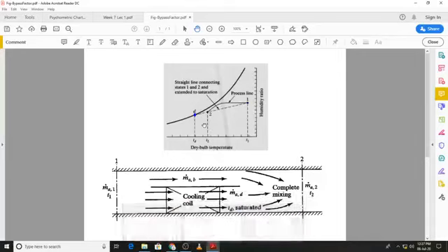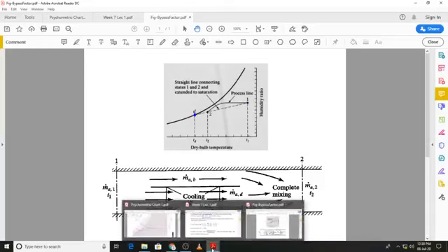So if we look at this figure over here, the difference between temperatures T2 and Td, that shows the effect of the bypassing of the cooling coil. If the air was perfectly cooled, that means state 2 would have coincided with state D, but because of the actual cooling in which temperature gradients are present, the air will leave at a temperature higher than the coil temperature, and that effect is represented by a bypass factor.